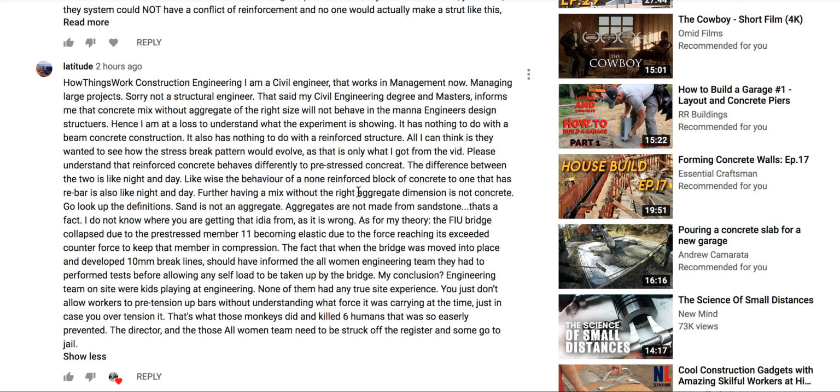If you want 4,500 PSI concrete and you're going to put it 6 inches thick, ideally you want to know that your factory, your manufacturer tested this concrete at 6 inches. They're testing it at 1 foot. They're testing it in 2-inch cubes. 2-inch cubes would be good in your favor. This is the point I'm making, is that the manufacturer is doing this.